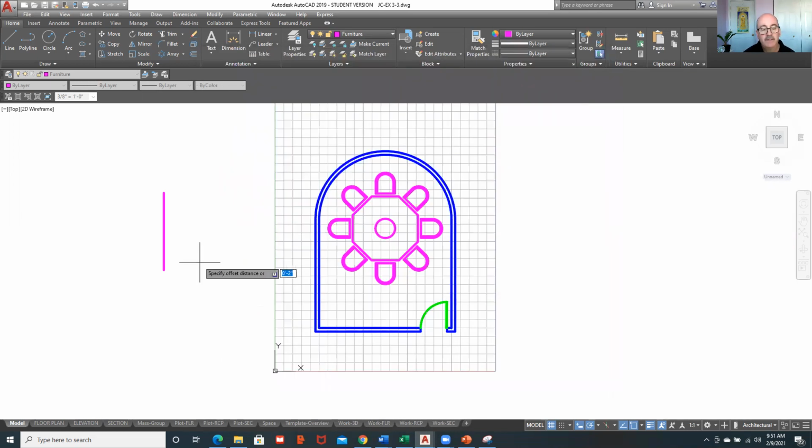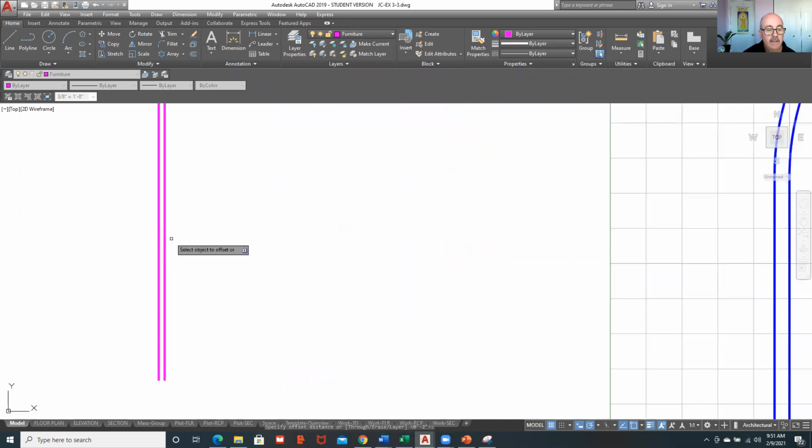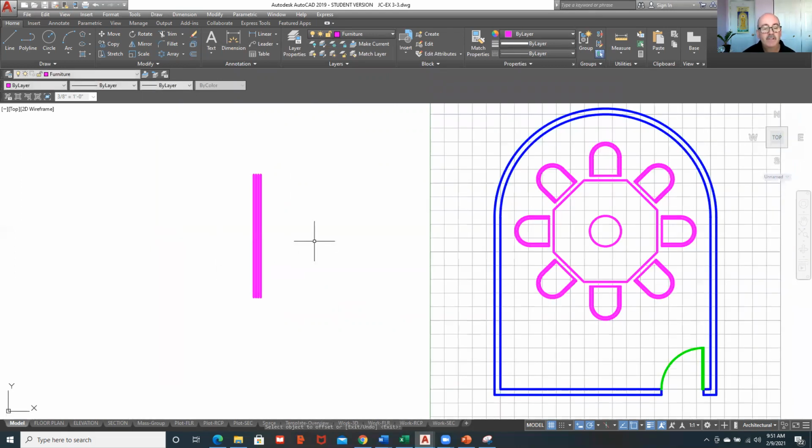So when we go with offset, I can say 2 inches, enter. It remembers the last value, and then it'll stay modal and allow me to just keep offsetting things. And it'll offset circles, arcs, lines. And then if I have something else like out here, and I don't know where the geometry is, and I want it to be offset through right through that end point, you can say offset down arrow through.